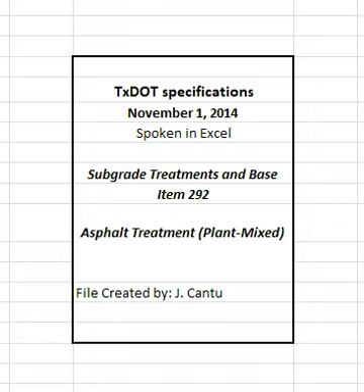felt paper. Determine the deleterious content of RAS material for mixture design purposes in accordance with TEX 217F, Part 3. Do not use RAS if deleterious materials are more than 0.5% of the stockpiled RAS unless otherwise approved. Submit a sample for approval to the engineer before submitting the mixture design. The department will perform the testing for deleterious material of RAS to determine specification compliance.